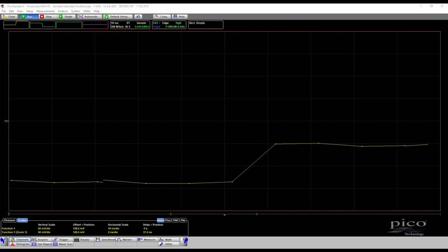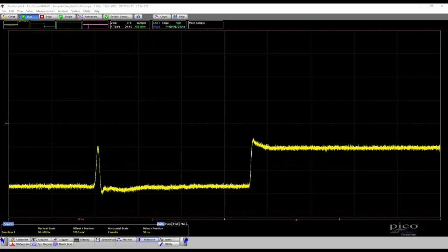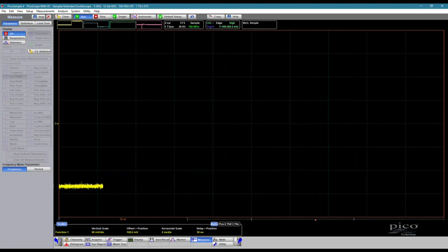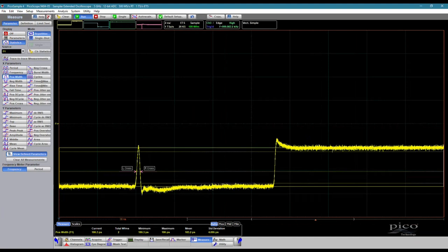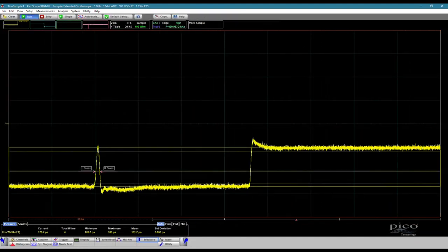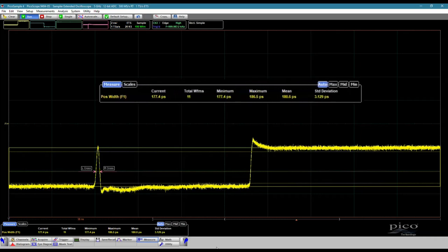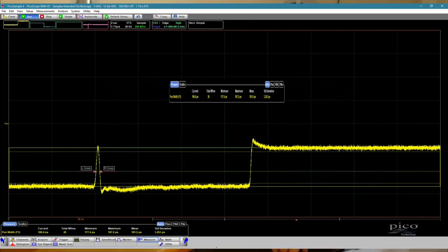All broadband real-time oscilloscopes and the SX-RTO use random equivalent time sampling on repetitive waveforms or clock-related data eyes to increase the sampling density. So, the SX-RTO gives us a new affordable price point for the broadband oscilloscope. Our high-speed signals do need to be repetitive rather than transient, but when they are, the SX-RTO will resolve high bandwidth signals with 12-bit and 1 picosecond sample resolution. That's 150 samples in our example pulse.